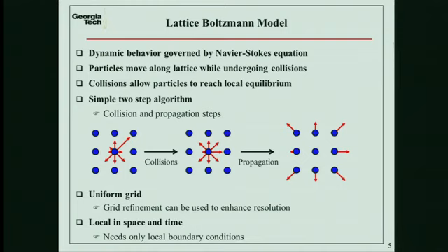Essentially, you can think about lattice-Boltzmann as a method where we have a set of fluid particles that propagate along a fixed-in-space lattice, right? They are organized such that in one time step they propagate to the next node, they collide, exchange momentum, and this way we can reproduce the hydrodynamic behavior of a Newtonian fluid, right?